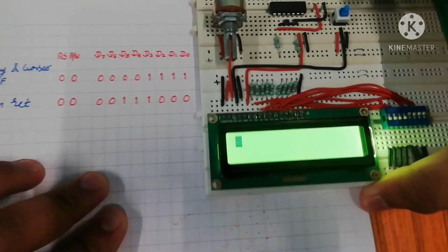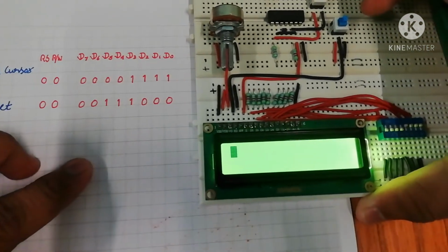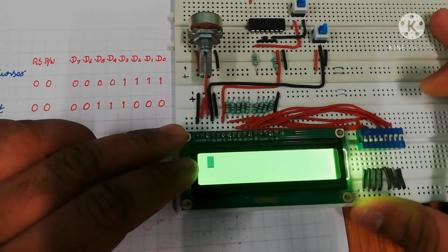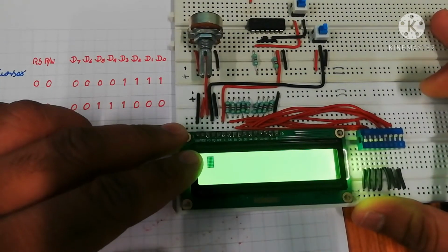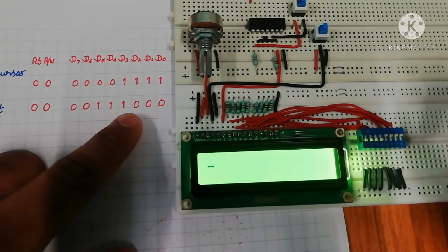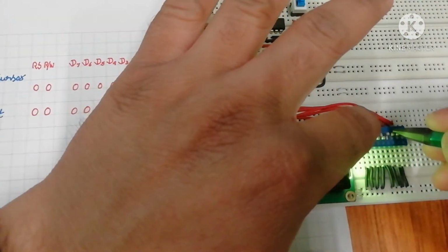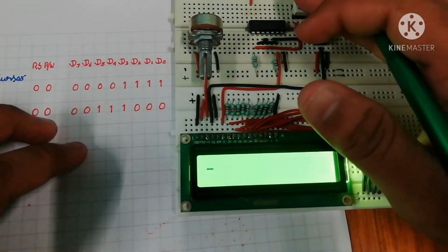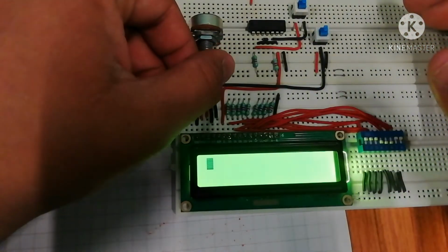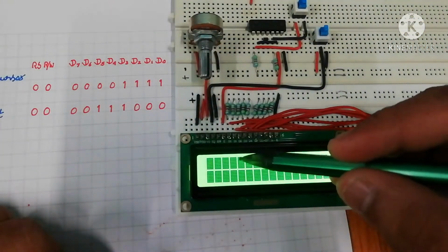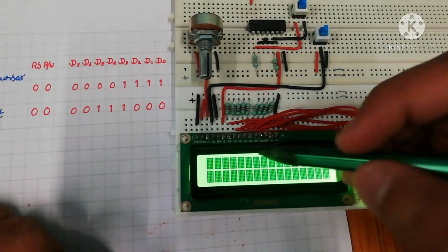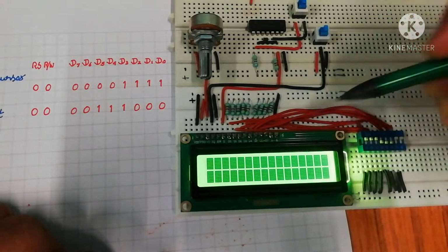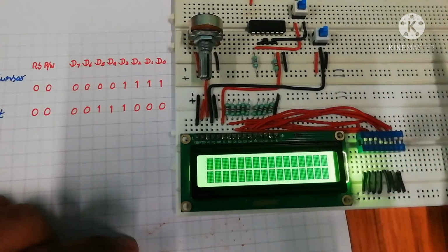Now the second command that we have to issue is the function set command. The function set command sets the number of lines used, the data bit length, and the pixel size. Looking at the opcode, pressing the enable pin, adjusting the contrast. See, the LCD has been initialized in 2-line mode and the pixel size is 5 by 8 pixels and the set data bit length is 8 bits, so the LCD is set to accept 8-bit data.